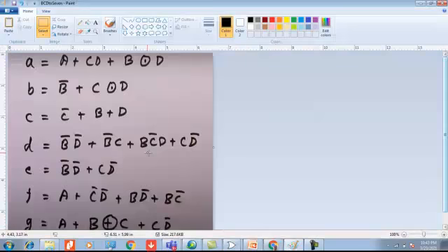So in a 7 segment display, you have 7 segments A, B, C, D, E, F, G, and you have common anode and common cathode connections. But here in Logisim, it works either way. As of now, keep in mind the simplified expressions A, B, C, D, E, F, G that we derived using K-map. Those 7 functions we are going to implement using Logisim.